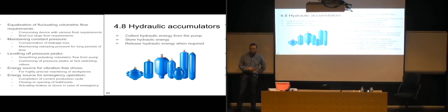So that if you have a system that is running, for example, in a mine, you might have a system running on tracks, so railway tracks, more or less, and you could have hydraulic braking systems on them. And if you lose power in your pump, you still want to be able to brake, not just have it run rampant along the lines. So then you can have compensators ready, so that if the pump stops delivering the correct flow and pressure, then you can use the accumulators to still use your brakes to stop the vehicle.